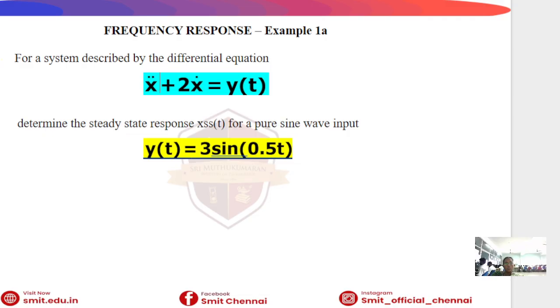In this table, the columns are terms, corner frequencies, slope, and change in slope. Terms means the terms from the transfer function; with three terms, we write three rows. Then the corner frequency values. Then the slope: j omega in the numerator means plus 20, in the denominator means minus 20. j omega square in the numerator means plus 40, in the denominator means minus 40.